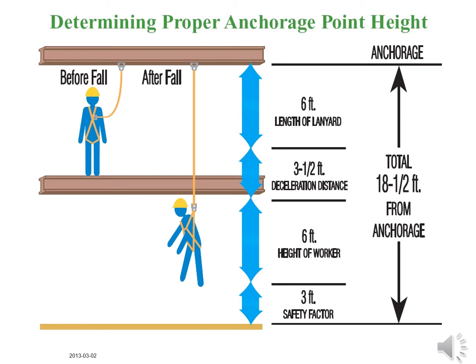Be sure that anchorage point for the tie-off is adequate. Normally, it should be able to support 5,000 pounds for each person that is attached. If you have any questions about your tie-off point, and if it is high enough or when you should use a retractable lanyard, see your supervisor or the safety department for help.